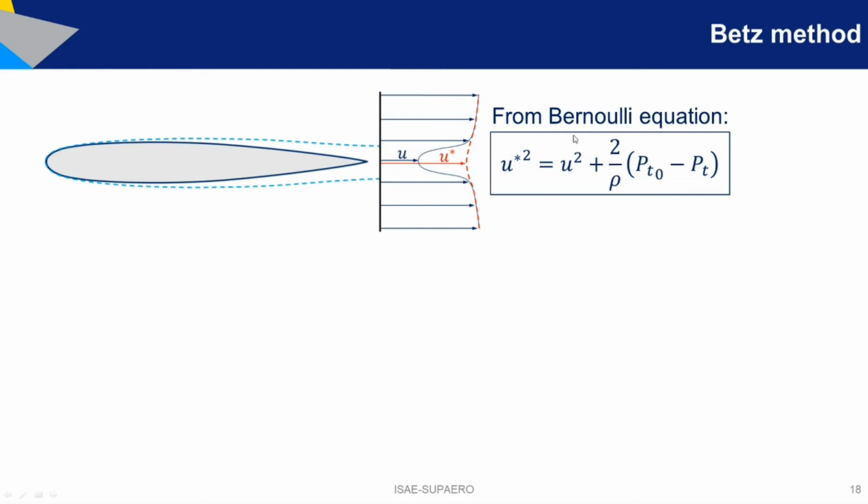So he's able to compute the isentropic velocity here based on the total pressure deficit at the Trefftz plane, at each point at the Trefftz plane. So this was the very first expression allowing us to compute the isentropic velocity. And then it was a major breakthrough because we can now perform the velocity decomposition.